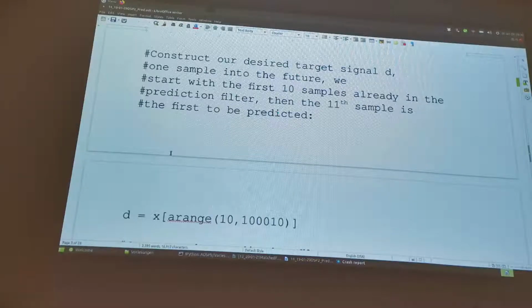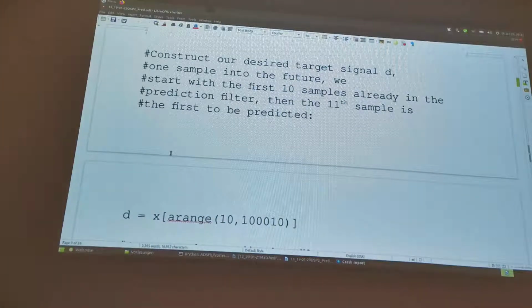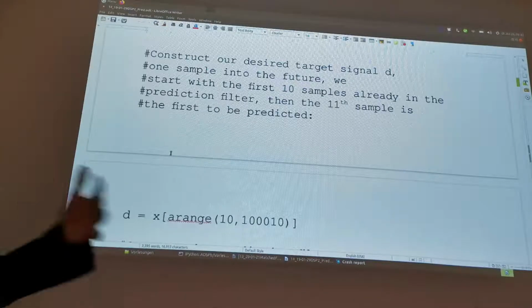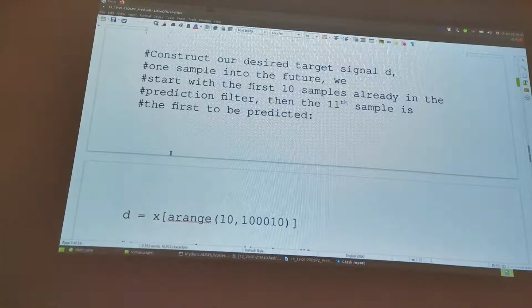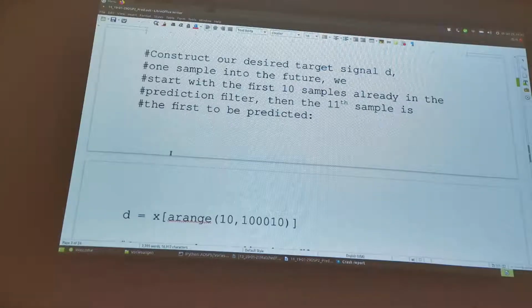So I'm taking the first 100,000 samples in this case sort of as a training set. Right? I use this as a training set for my coefficients, H, but I then can apply this filter to the entire file. Right? So basically I'm taking the second half of this audio file as a test set, where I see how it performs.